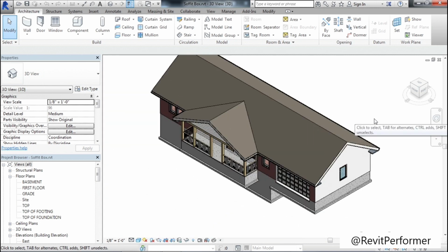You can use a regular Revit family, or you can model a wall there in place. But I really don't recommend either one of those tactics because they're both solutions that aren't very adaptable. One of the things that I like to do, though, is use walls because walls are fairly easy to modify. They can have the right material associated with them. And then if the roof or the soffit would make any adjustments, the walls can follow them along.